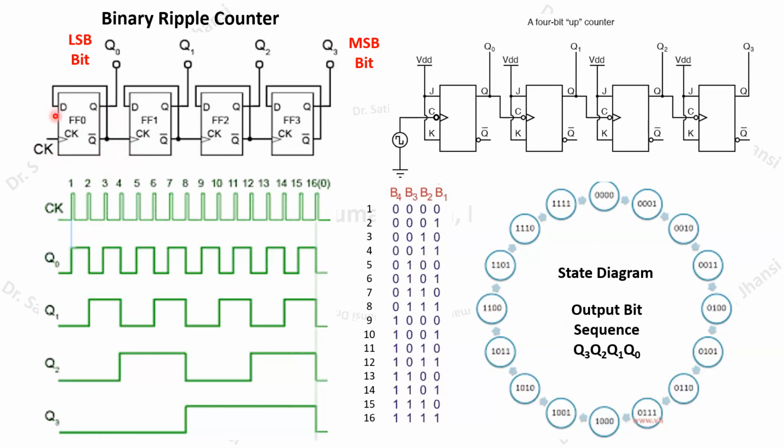So when the next clock pulse will arrive, at that time you can think of, because it is actually connected to your 0. Now Q bar is 0. So that time what happens, this D will be receiving a 0 as the input, and when the next clock edge will arrive, at that time this output will become again 0. So here you can see that it is initially 1 and then it is becoming 0. Okay, this way it is going to be 0.